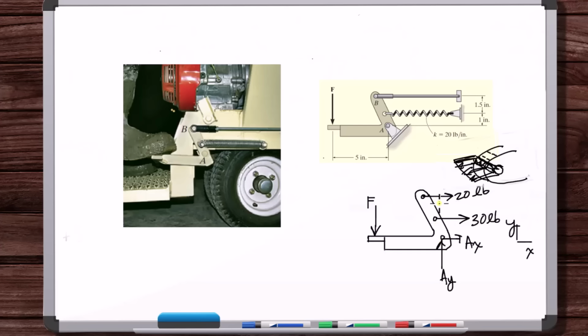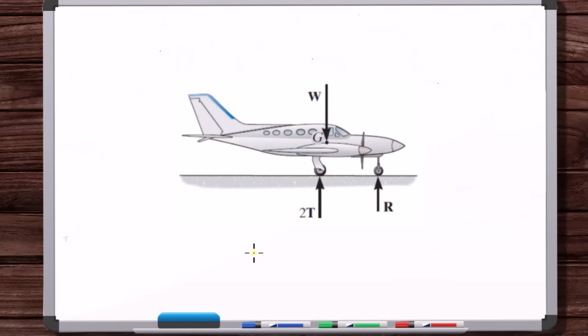And if that's the case for all of the forces on the free body diagram, then that's why you can do a planar free body diagram. It's like you're looking at that center plane. You're just projecting everything onto that center plane. All right, here's a planar free body diagram. Why does this free body diagram work?